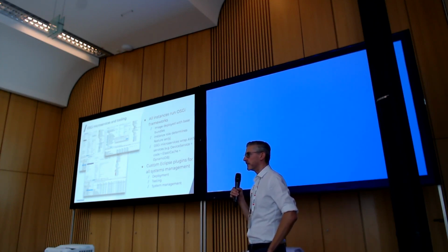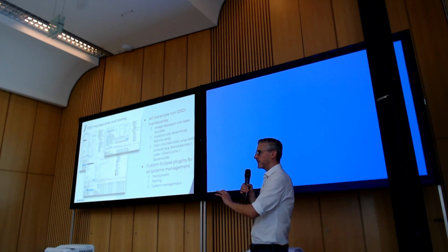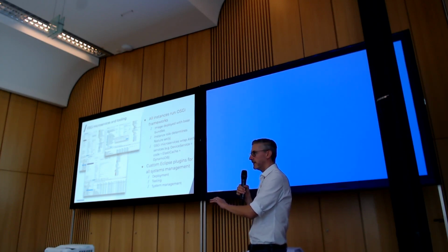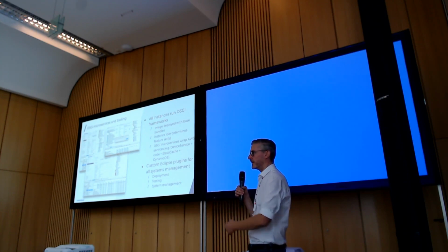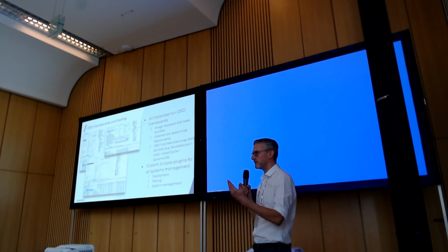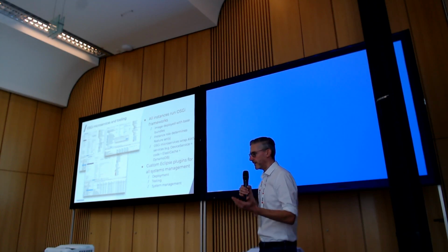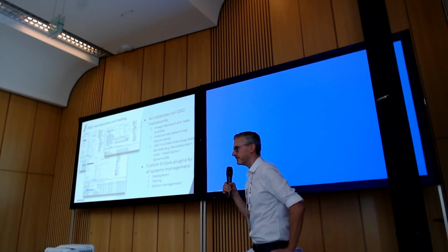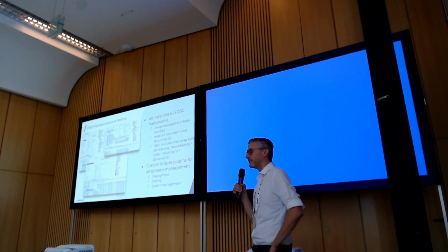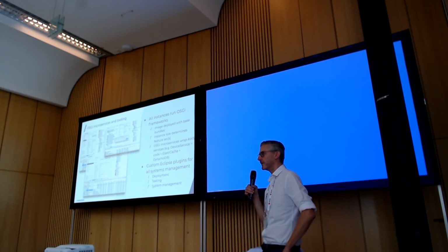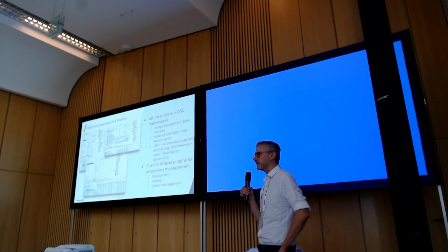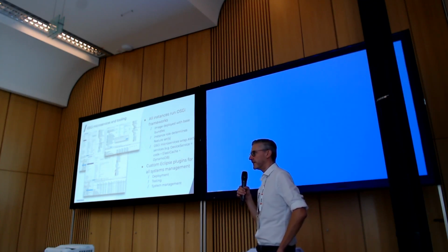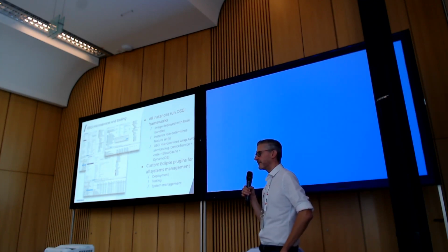It's really small. The implementation of the ThingStream service in OSGi is obviously written in Java, so significantly bigger, but there are implementations of it for a number of different platforms, and you can get a C SDK that will run in 12K of flash and about 4K of RAM. So really small. There's not much in it. There's modem management code, a bit of data processing, and a bit of connection management. There's not much.